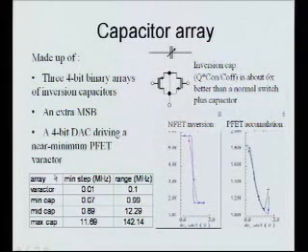Anyway, this just gives you an idea of what I was saying. The varactor is not very linear, so it has a range of about a factor of 10. Its full range gave me about 100 kilohertz, which is more than the LSB of the next array up, so I know I have overlap. I can cover variation. So the columns are: the minimum step is my LSB, and the range is essentially if I switch that array from all the way off to all the way on.